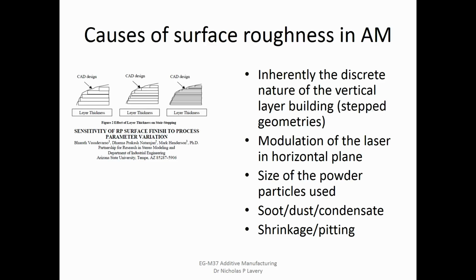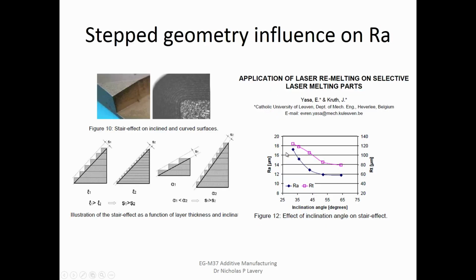As you go up, you build the layers up discretely in 30 micron or 50 micron. If you're trying to fit a curve, then you're going to have some sort of anti-aliasing, as they have in bitmap. So this stepping gives you an underlying surface roughness, beyond which all you can possibly do is hope that by polishing it you can get rid of it. But again, then you're back to that original problem of how do you polish complex underlying surfaces. The angle of inclination, so if you were to do...